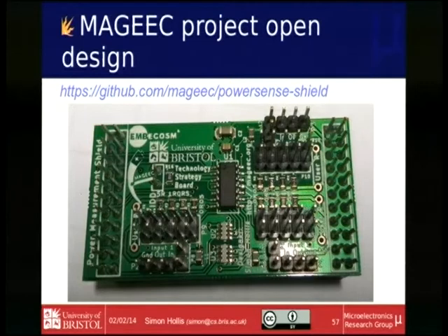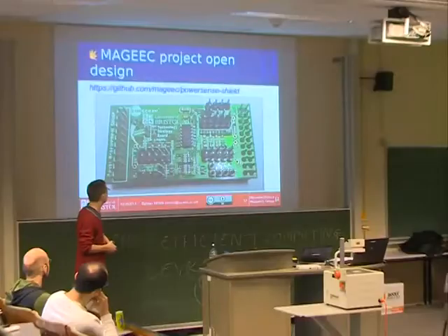If you zoom in, and in my hand, this is the amplifier in the middle, the biggest part of the device. We've got a big selection of different shunt resistors that you can insert by connecting to the board. So you have to do some soldering. All you have to do is connect your power supplies into some pins here. So you have to break the power supply trace on the board, take 2 wires out, and push them into here and here, and then that's it. Then you set some jumpers, little nice red jumpers we've got, and this will then do all of what I've done. It's designed, very carefully controlled.